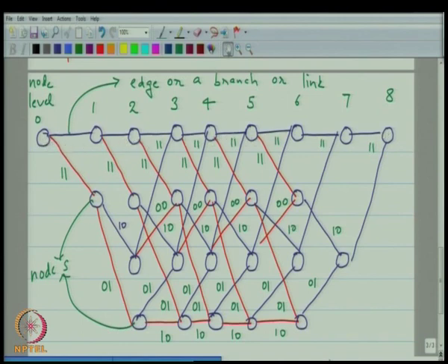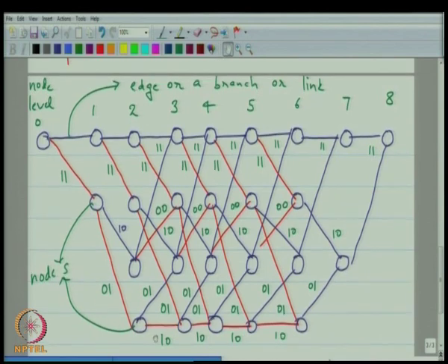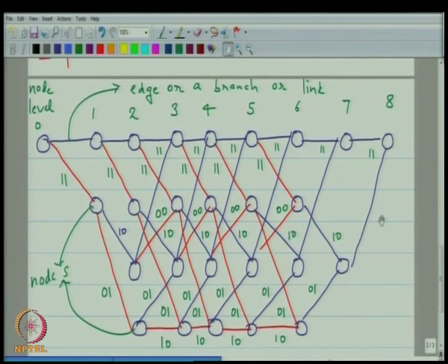On the other hand, if I feed the encoder the all 1 message sequence, then I will be tracing this particular path in the trellis. Supposing it is alternating zeros and ones, so that is 0, that is 1, that is 0, that is 1. Sorry, there is no 1 here because there is no option for a 1 at the end. But you get the idea. In this trellis we forcibly forced the last two symbols to be 0, so that was the reason why I could not get to a 1.